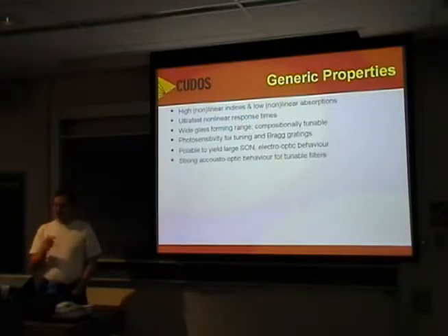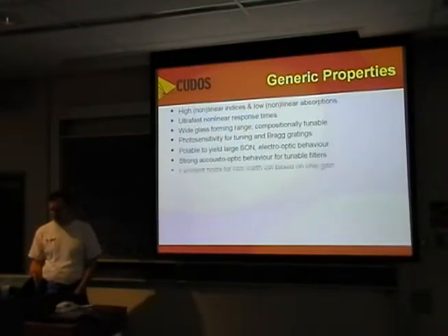Interestingly, tellurites and chalcogenides are also strongly acousto-optic, and in their respective transmission windows have extended material for acousto-optic cells. So that allows you to build things like very wide bandwidth tunable filters. Again, there's work to be done to exploit that in a guided wave implementation, but it's another opportunity.